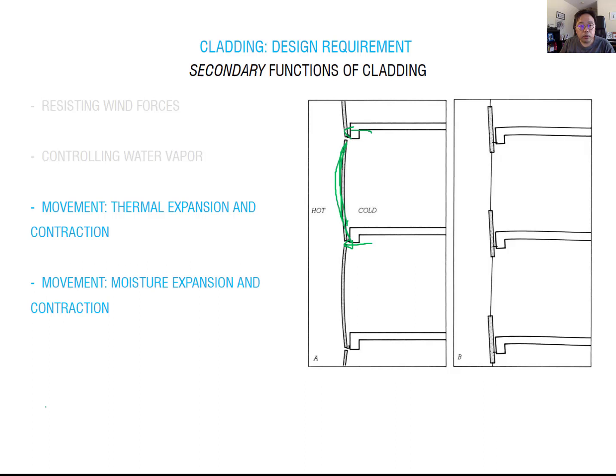And also between the cladding and the slab edge, you can have some gap because of this keep pushing and shrinking, and it makes a joint and gap between. So when you make a bigger gap because of the movement, there is a lot of airflow. It means you're losing heat energy. Also there is moisture transfer, making condensation issues, also air tightness and water issues. So that's why you have to be very concerned about the movement.